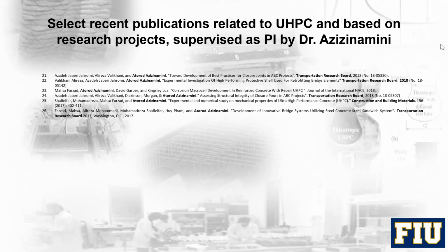Moisturizing the normal strength concrete is not like spraying water 1 hour before placing the UHPC. You have to use wet burlap or so, maybe 24 hours before placing the UHPC, to prepare the surface, because there's not that much water in the UHPC, and it's going to soak it up and can cause cracking.